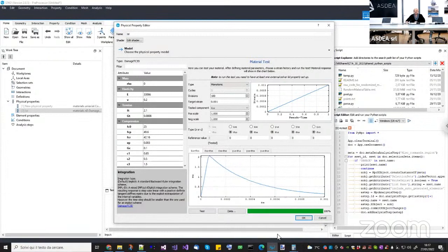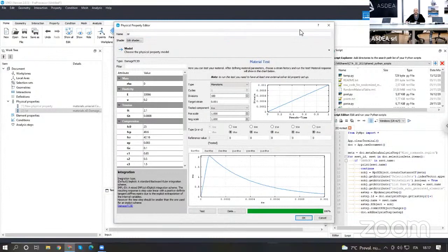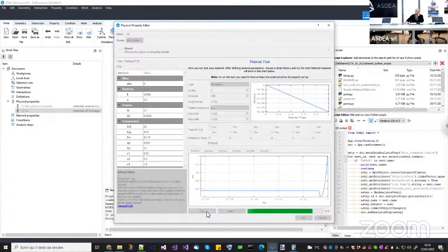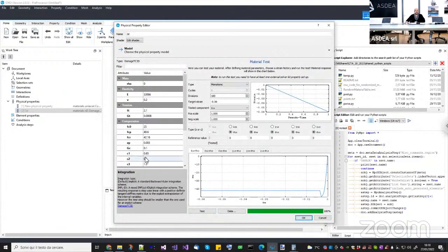Okay, now of course, the other test was going down to 0 here, but because it was linear. Okay, so if we do a simple annotation here, it was linear up to down here. Okay, now in this case it is exponential, so it will reach 0 slightly forward, but it is pretty much the same. Okay, so in tension it is fine. Now let's test the compression. It was minus 0.06. And let's see if it has the same phase more or less. No, because of course we need to increase this fracture energy. Okay, now we can keep on increasing it until this value reaches 0.05.